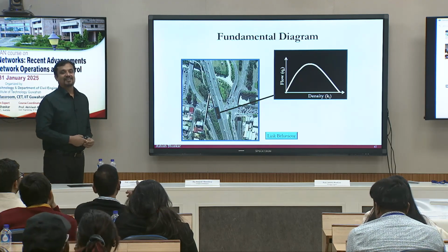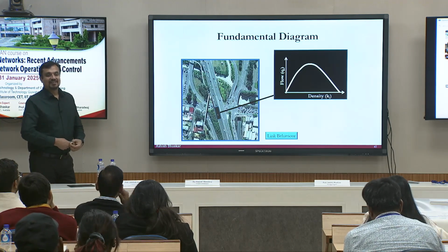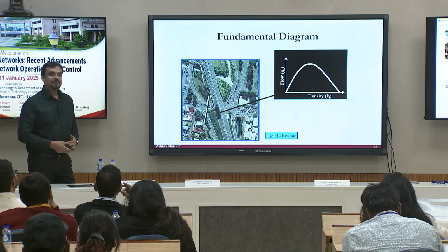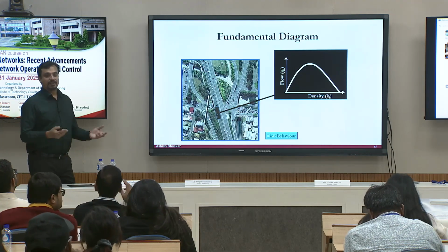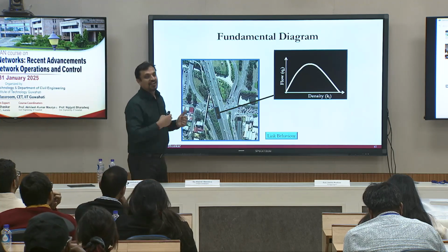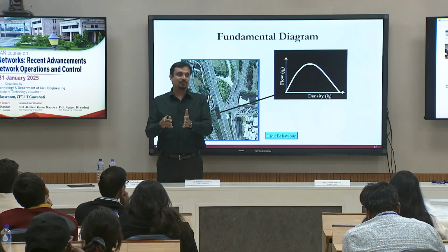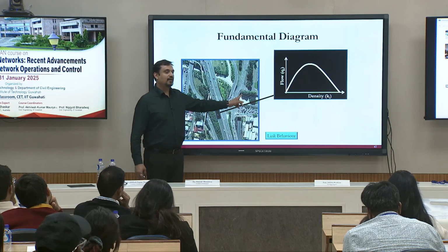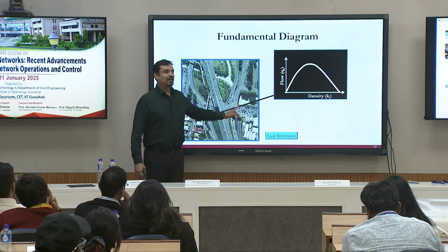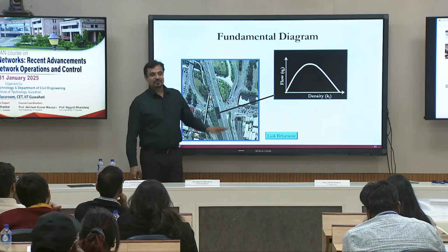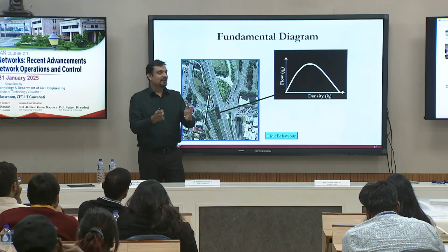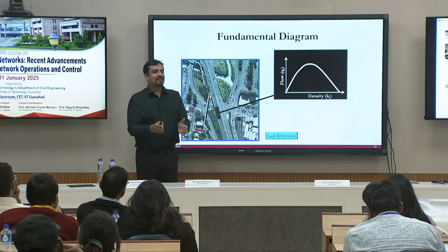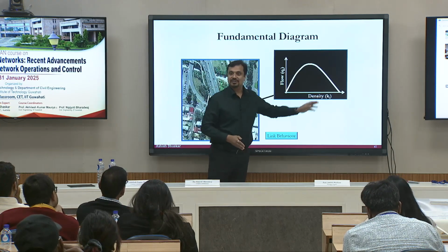But if we talk about capacity during green time, then it's another question you have raised. How will the shape look if I only plot my data points during the green time? So let's say I'm only going to calculate the flow and occupancy during the green time. At that time, I will not do any calculation during red. So let's say I have green for 60 seconds, red for 60 seconds, then green again for 60, red for 60. Only present the data for the 60 seconds of green. It will have somewhat the shape you see, perhaps.